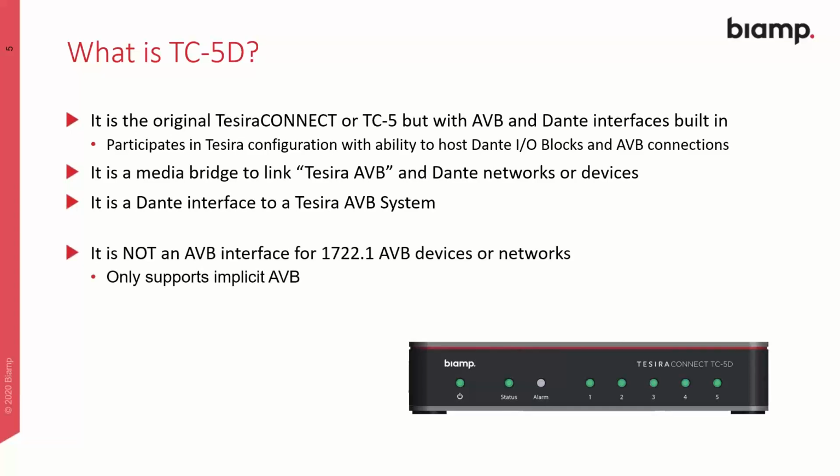It is not, however, an AVB interface for standards-based 1722.1 AVB devices that are not Biamp. So only implicit AVB connections are supported within this device. It will also not host other DSP blocks, so meters, level controls, etc., like your server class devices. It will not host those, only Dante I/O blocks.